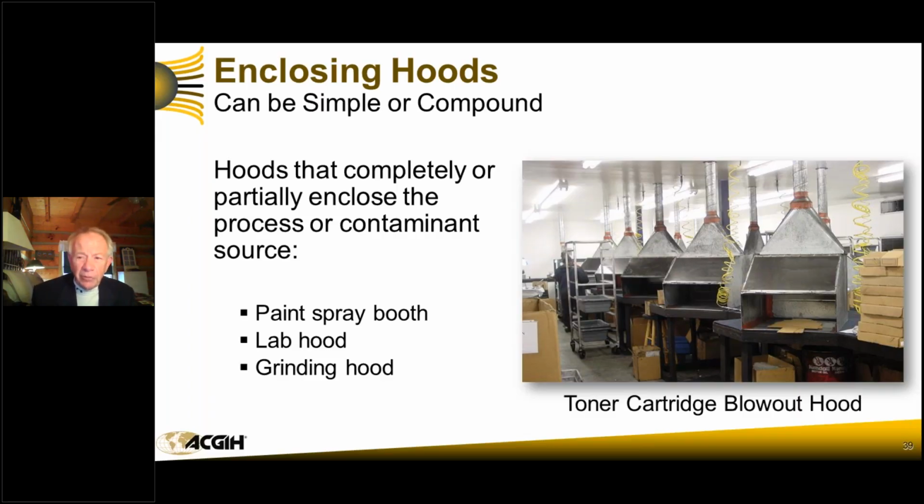They protect people from exposure to toluene diisocyanate found in a paint spray called DuPont Imron paint, and they do it very effectively. The TLV, as I remember, on TDI is 0.1 or 0.02 parts per million. We're talking about something that is highly toxic. And when was the last time you heard somebody succumbing to TDI in a paint spray booth?